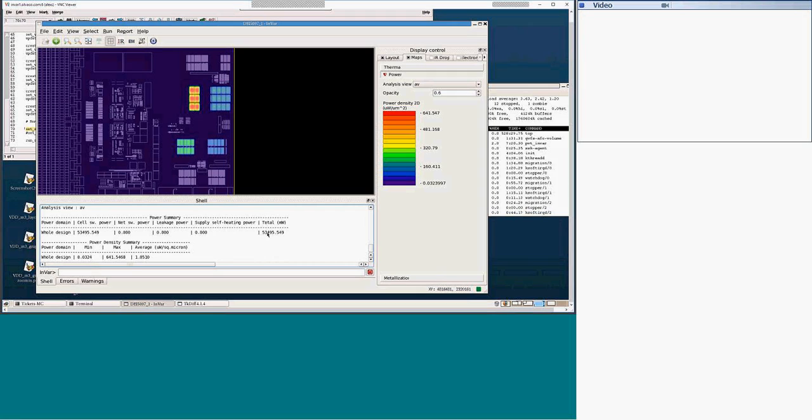Because if you run the SPICE netlist alone, you would get the same 53 watts of total power. Maybe settings for inputs or something else was screwed up. So at this moment, I assume that input data may not be correct. And I hope you can check it and provide the correct SPICE netlist with the correct DSPF.